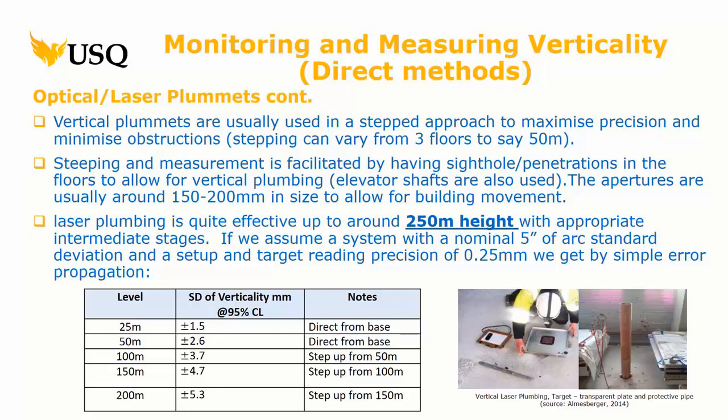Now, outside when you're doing surveying on a floor or even the first few floors, right, you can put redundant points. But when you're getting up here, redundancy means putting another hole in the floor, another pipe. Because 2 points, think back to that plane, if you've got the 2 points, it defines a line, right? It doesn't define exactly where the plane is. In theory, that floor could be floating like this, right? So you could put the 2 points up there and you could level them and go, it's not doing that. I can see it's flat, right? Which helps. Usually you would aim to have at least one more redundant point.